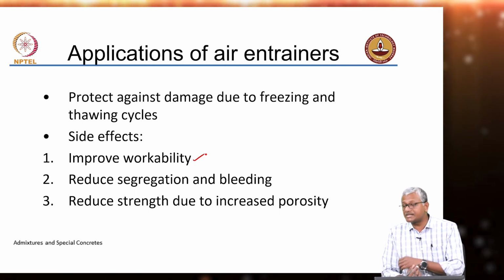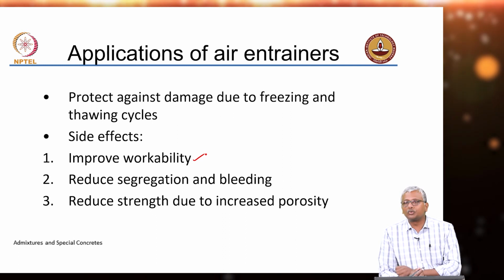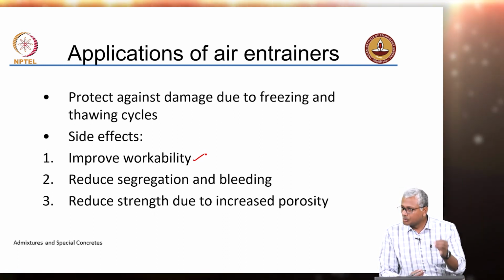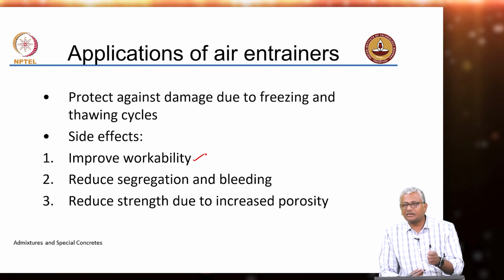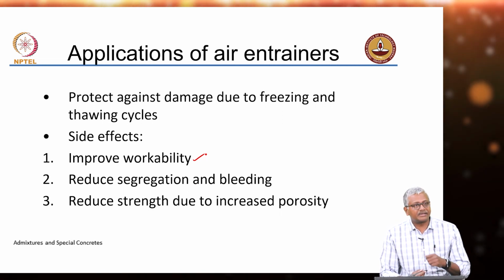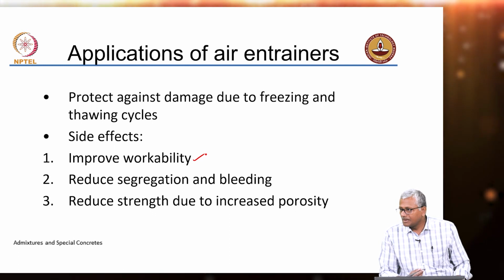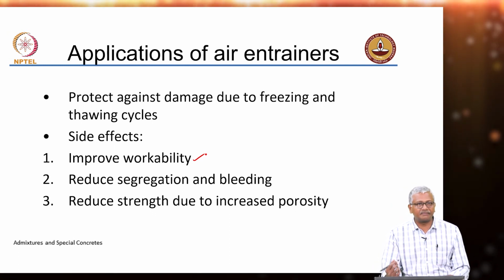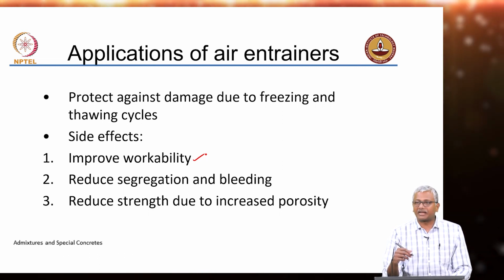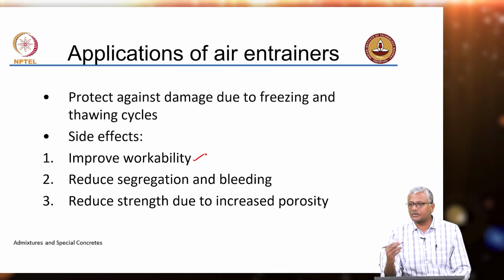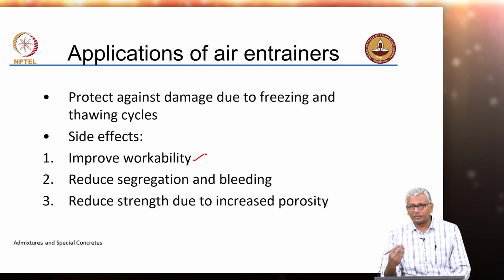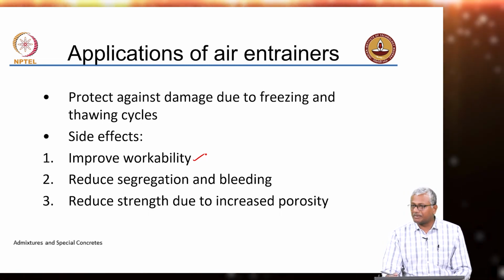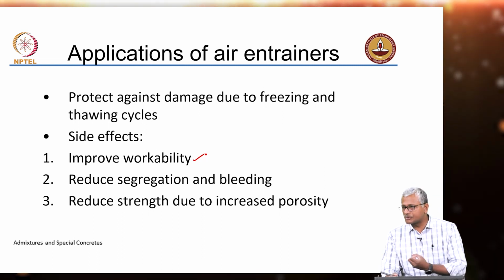And in some instances, indeed, especially when you do plastering, many people use air entrainers for the purpose of making the concrete a lot more consistent and easy to apply, rather than actually using it for freezing and thawing damage, because plastering is done everywhere. Using air entrainers in plaster is a very nice way to make it smooth to apply, with better consistency to apply.